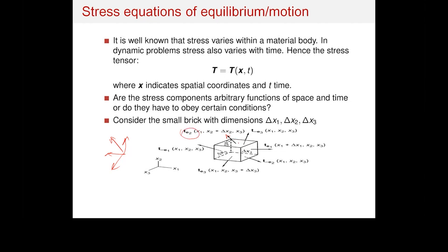Now you have stress vectors acting on every face of this cube. This is an infinitely small cube, a continuum particle. Now these stresses will need to be in equilibrium with each other, but they would also need to be in equilibrium with the body forces. Let us assume that this body here is in motion, so it will need to observe the equation of equilibrium of momentum, the equation of Newton.